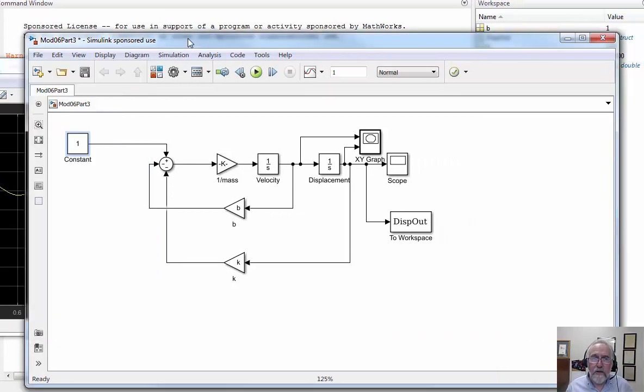So the nonlinearity we're going to look into is a nonlinear spring. And if you think about how most springs work, certainly in compression and in extension both ways, as they get closer to the solid height as you press them together, the coils start getting closer to each other, and it becomes harder to compress them, so it gets stiffer. Same way when you're pulling it apart, when the coils start getting too far apart, you're actually starting to pull the wire of the spring, and it gets stiffer. And one way to represent that variation in stiffness is by implementing the spring stiffness not as a linear function but as a cubic function.